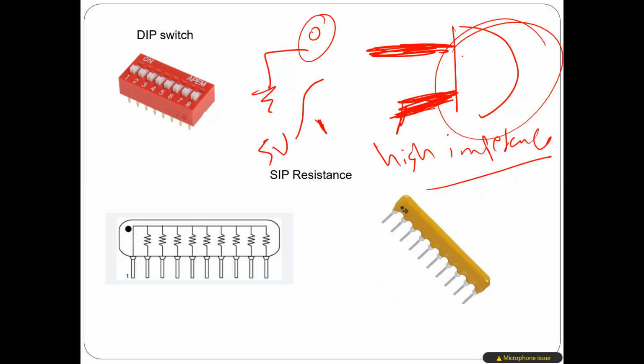For sure, this changes; you need to read the data sheet. But if it is floating, meaning it's not connected to anything, or high impedance, it will be taken as either 0 volt or 1 volt, one of them. Sometimes it depends on how the chip is designed. Sometimes it's 0 volt, sometimes 1 volt. So you need to look at the data sheet. I think one of the questions here is about how you can connect the switch.